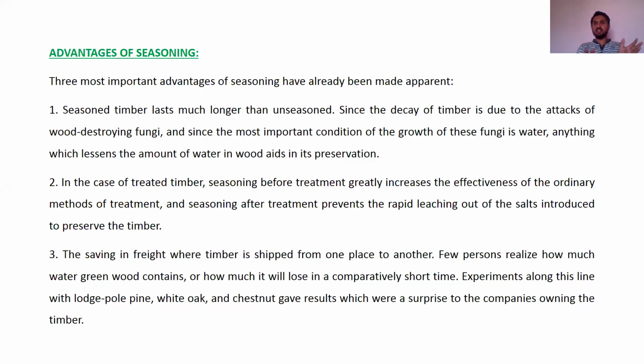Suppose in the first week, it can reduce by 10% or 20%. The moisture content in a natural way, around 20% of the moisture can be reduced in the first week. But in the second week, again it will not be 20%, it will reduce somewhat. But after the treatment, the salt which has been introduced to preserve the timber can be leached out in a proper way. That is the advantage actually.